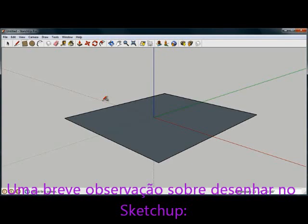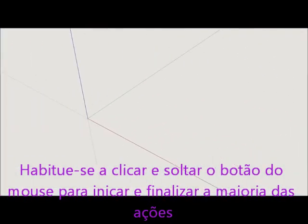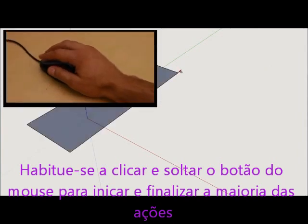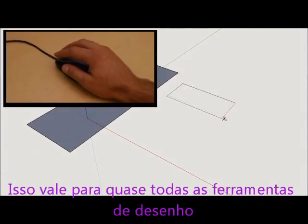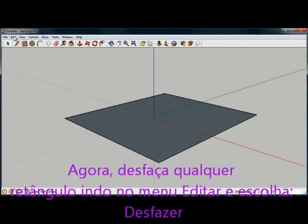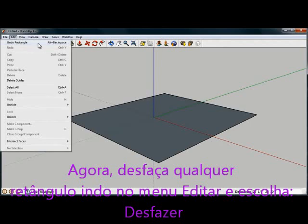A quick note about drawing in SketchUp. Get in the habit of click and releasing your mouse button to start and finish most actions. This will be true for almost all of the drawing tools. Now undo any rectangles by going to the Edit menu and choosing Undo.